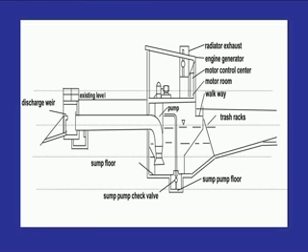We can have this kind of pumping installation for pumping large storm water flows. Here the water is coming from the storm water drain and there is a trash rack here and it enters through the trash rack, and we have a pump here. We have to maintain a certain minimum depth of flow, and we have a sump here, a sump pit. We have provided a pump here also to drain for maintenance purposes.